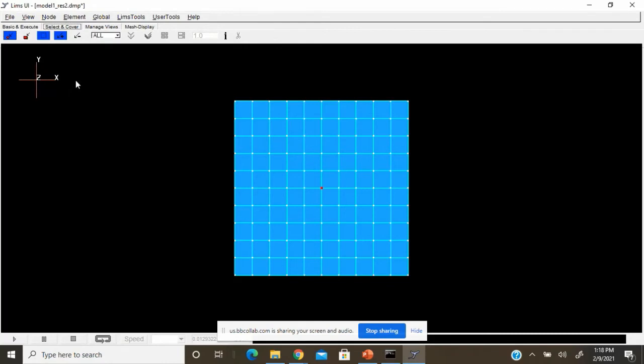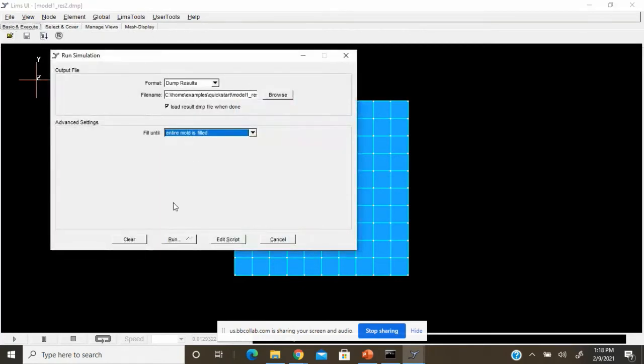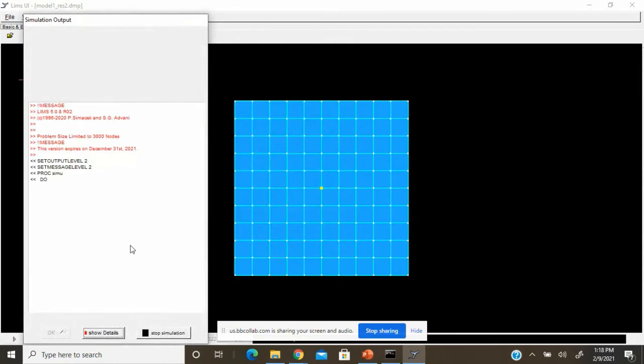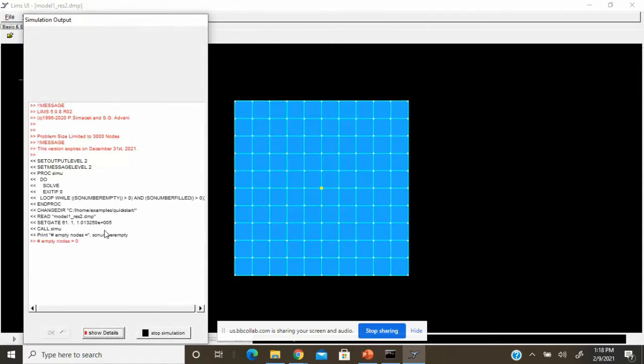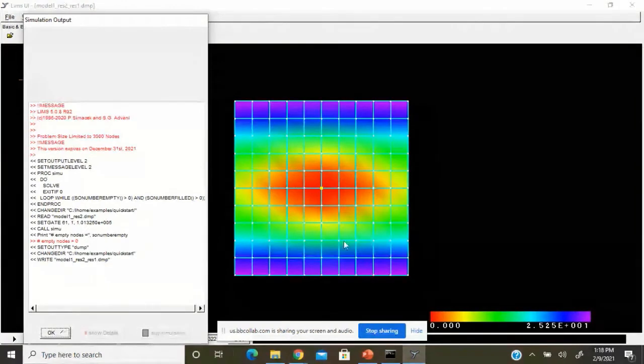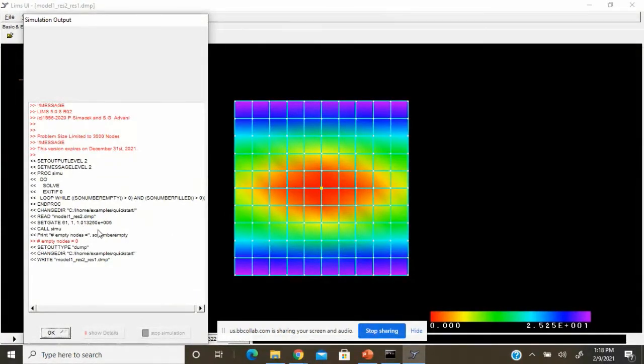Once you give that, you set your viscosity, which is already set here. You go and save and run the simulation. So you can see here that we have set the node at 61. You have seen the pressure that is set, and you can see that the mold filling is happening according to the anisotropic nature of the composite itself, or the fiber fabric preform.